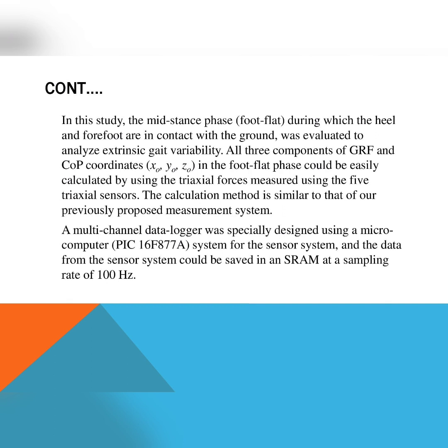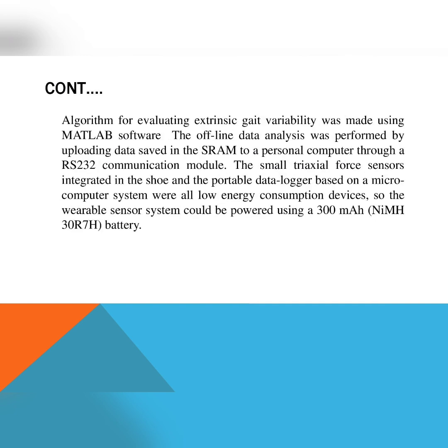A multi-channel data logger was specially designed using a microcomputer system for the sensor systems, and data from the sensor system could be saved in SRAM, static random access memory, at a sampling rate of 100 Hz. Algorithm for evaluating extrinsic gait variability was made using MATLAB software.